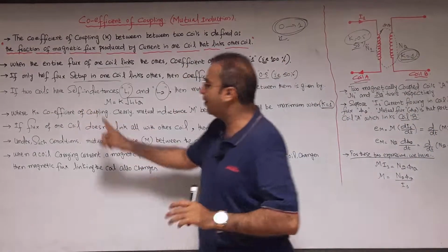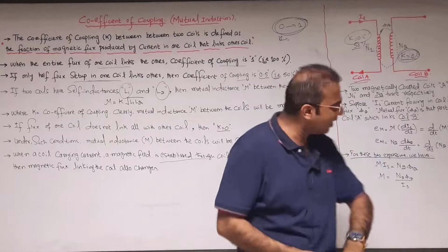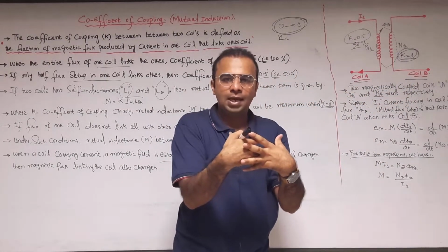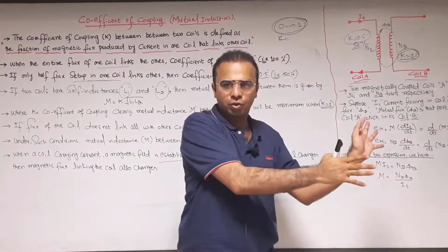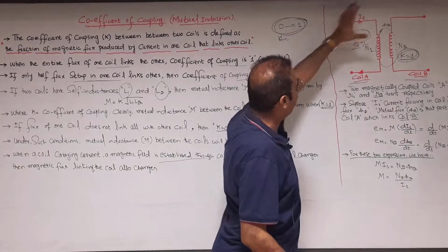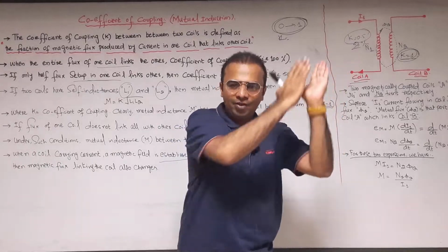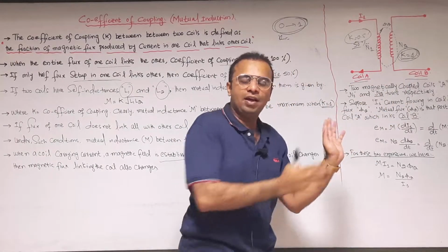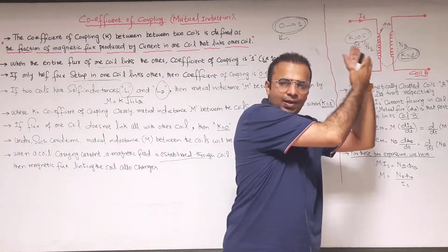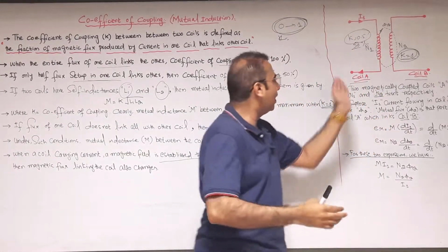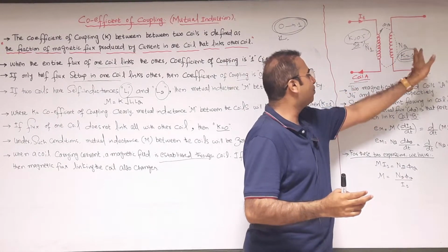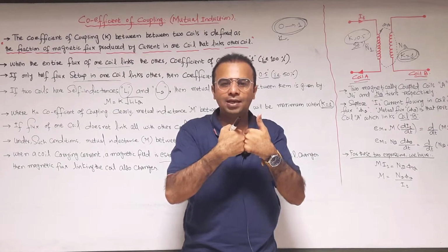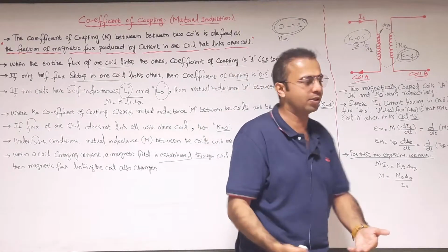Now if the two coils have self inductances, and both coils are magnetically coupled, a mutually induced EMF is produced. If coil A is carrying current from the main supply and this current changes, then an induced EMF is produced in coil B according to the magnetic linkage or coupling. This is called the mutual induction process.